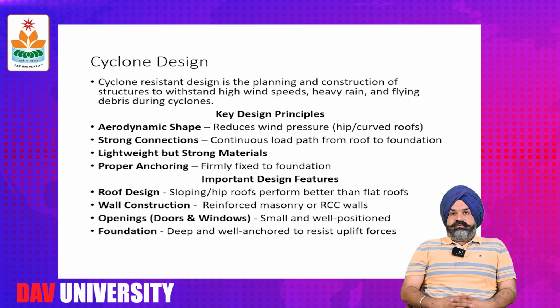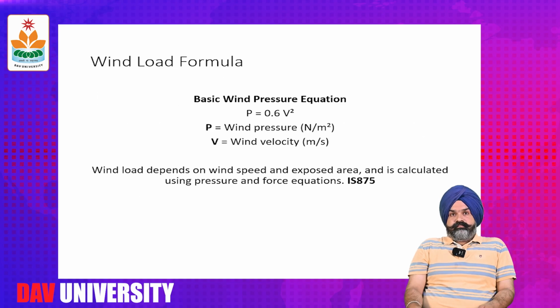Now coming to cyclone design. Cyclone resistant design is the planning and construction of structures to withstand high wind speeds, heavy rains, and flying debris during cyclones. The key design principles are aerodynamic shape, strong connections, lightweight but strong materials, and proper anchoring. And the important design features are roof design, wall construction, openings like doors and windows, and the foundations.